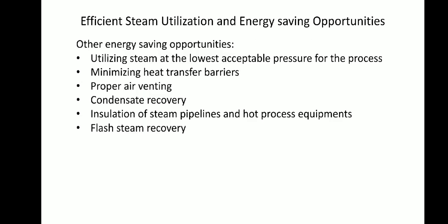Then other energy saving opportunities are utilizing steam at the lower acceptable pressure for process, minimizing heat transfer barriers, proper air venting and condensate recovery, insulation of steam pipelines and hot process equipment, and finally, flash steam recovery. These are the energy saving opportunities of steam pipelines.